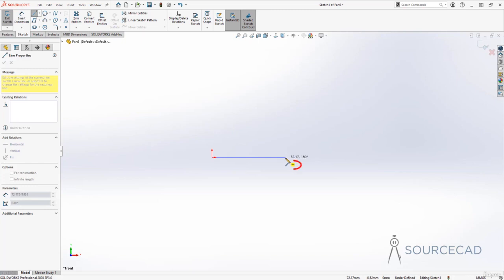Another thing is this yellow box with this line icon. Now that's a constraint. So in this case it is applying the horizontal constraint on this line, which means if I make this line now, if I click here, I'll end up with a line that will remain horizontal, because as soon as I clicked, now you can see that we have that horizontal constraint added right here. Not only that, we also have a new constraint called coincident. Now that constraint will keep this line connected at the origin. So since we started with the origin, SolidWorks will ensure that it remains connected at that point.